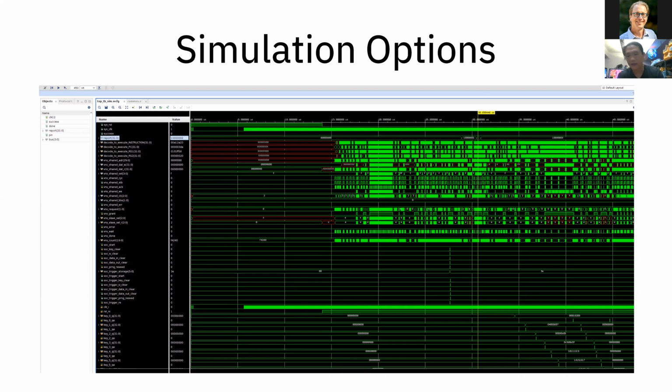Also, this is the simulator I've been using the most recently. This is the Xilinx proprietary XSIM simulator, but it can plug directly into this toolflow as well. And this here is an example. I've got a full VexRiscv CPU booting with peripherals, and you can run it at something like 10 kilo instructions per second, which is enough to boot into the bootloader and test actual hardware using code loops, as opposed to writing a bunch of test bench scaffolding to simulate the CPU.